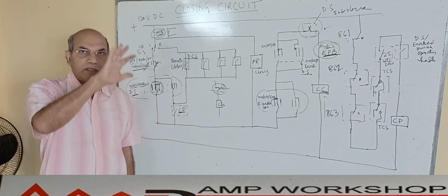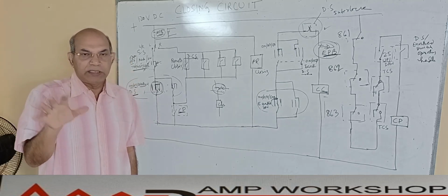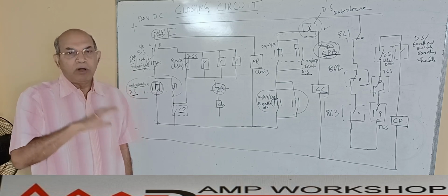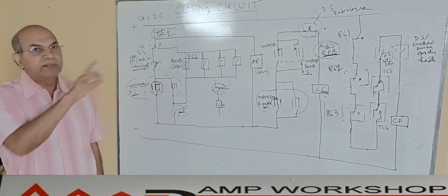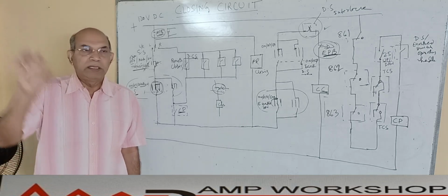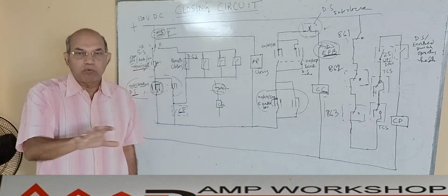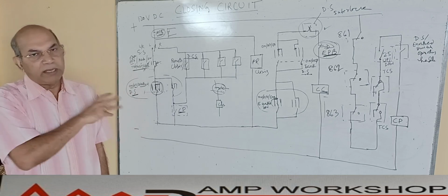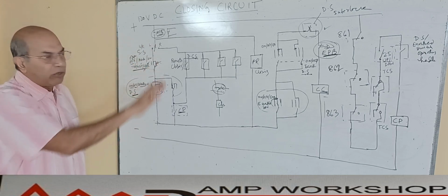from the local, on the switchgear panel, all the protection relays are there, all the interlocks are there, all the healthy indications are there. I can see everything on the panel. Relay is healthy, indication light is healthy, breaker close partition, everything is there. So I can close locally by observing all these things.